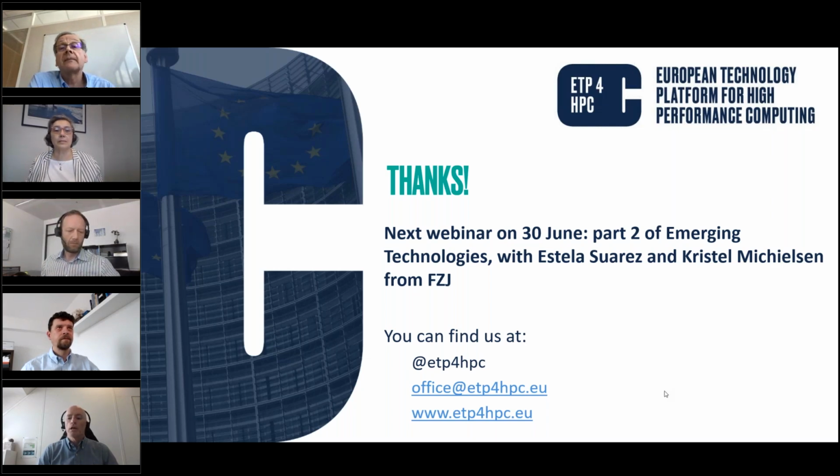I think the other thing is, there are a lot of things we can do at the software level, looking at compilers and shared compilers across acceleration, especially in the open source community. But from a hardware perspective, what you have to look at is latency and bandwidth, and how sensitive you are to them. If we split the elements in the chip, our latency can potentially be higher, and certain workloads are sensitive to that and certain others aren't. So adapting architectures so that you can share memory across compute elements, or finding ways to address these latency concerns, is the important piece.